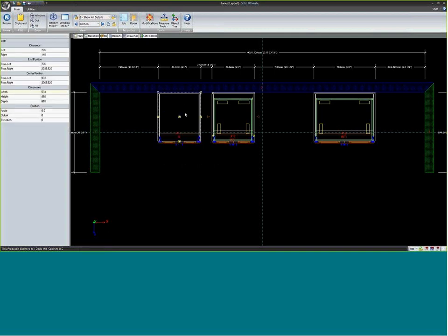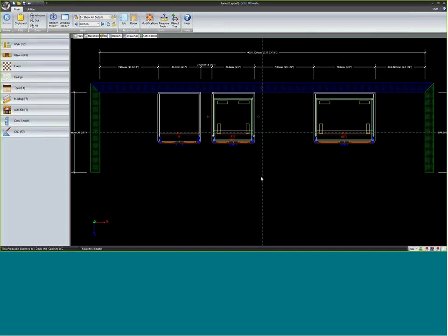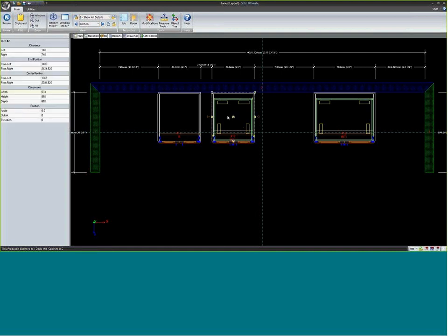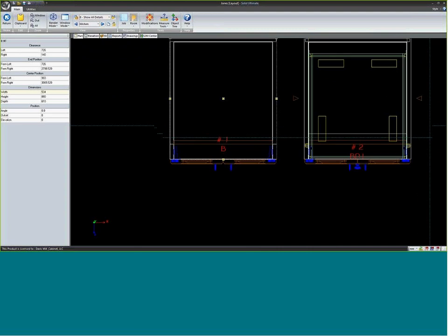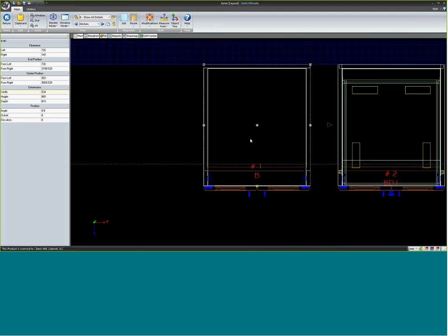So on a cabinet, for instance, if I want to have a run of cabinets and on one cabinet, say I wanted a built-in chair, I wanted it to be an inset face frame, but everything else is a Eurobox. I can do that in Cabinet Vision just fine. But my room is going to be set as a Eurobox, but I override this one. Let's do this cabinet. I'm going to change it to a beaded inset face frame.